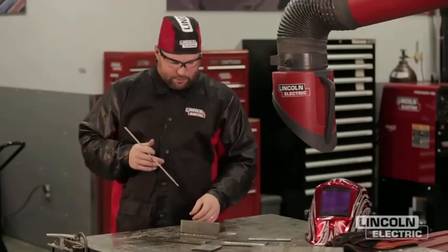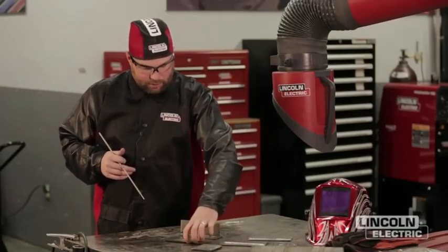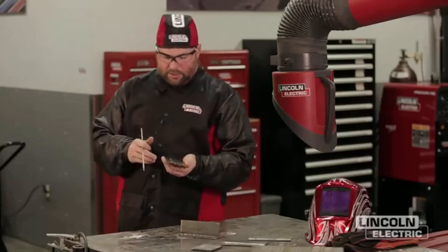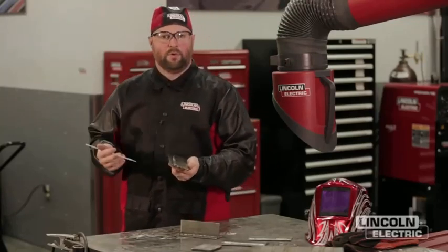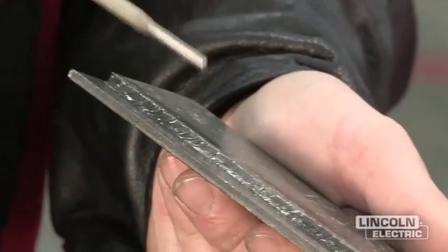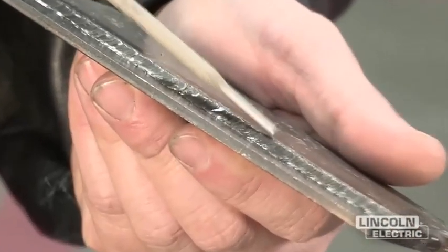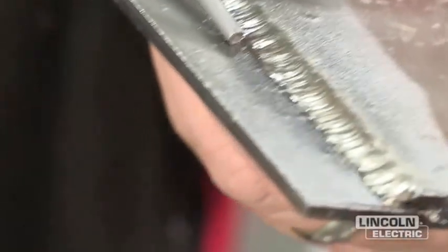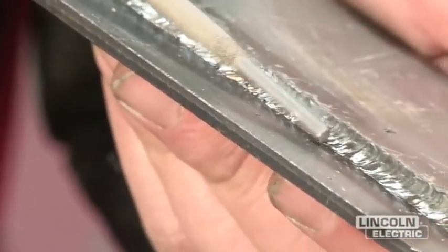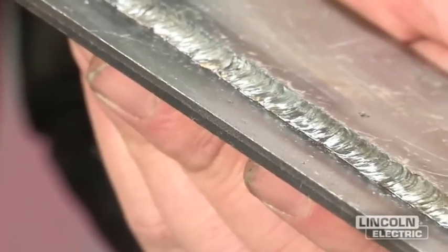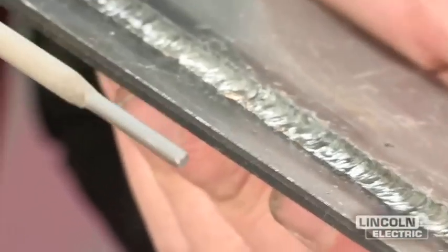And one of the last ones that we look at is the wash-in, and we'll select this one here. This is a lap joint, but when we refer to wash-in, if we go back and look at the toes of the weld that we talked about, we want the transition at the toe of the welds to blend in smoothly with the base material. If it doesn't transition smoothly or have good wash-in, you could possibly get a stress riser there.